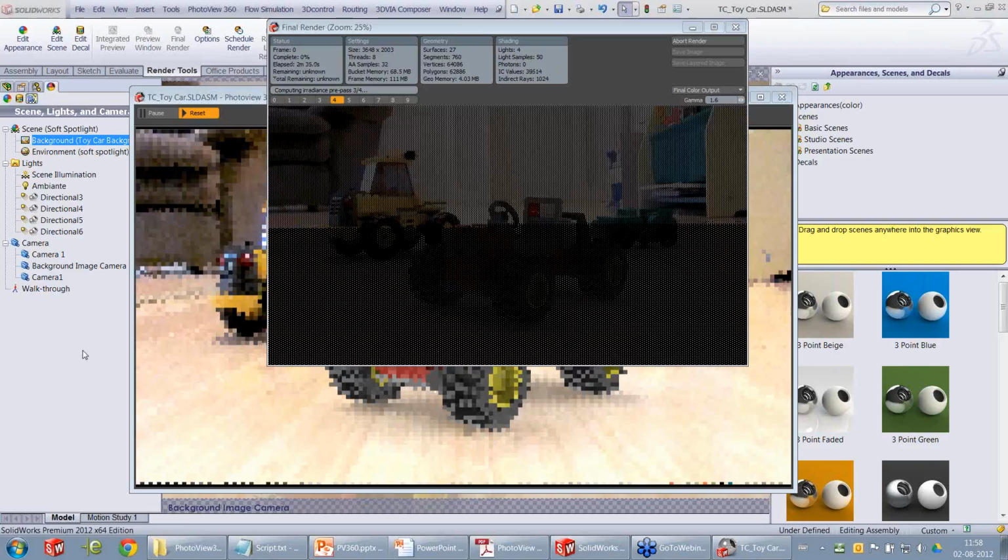I have one more question regarding how to mask a decal on a curved surface. Yeah, it's basically the same exact process that we followed. The surface has nothing to do with it. It's all about the selection color mask that you pick on the left in the property manager.